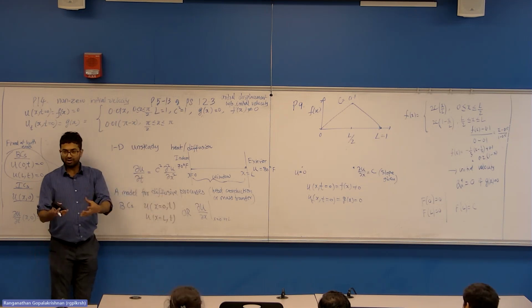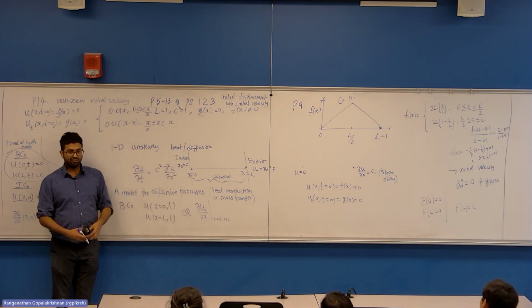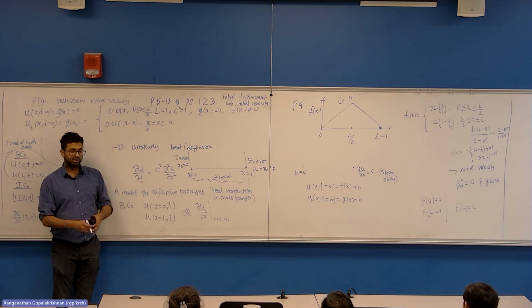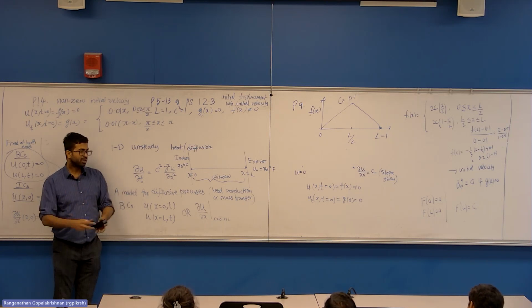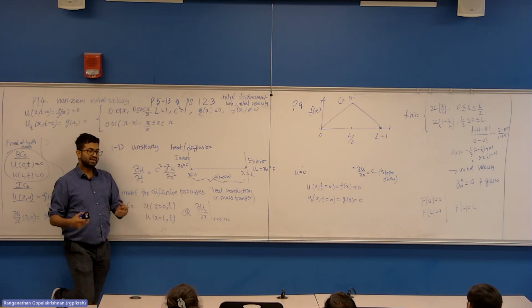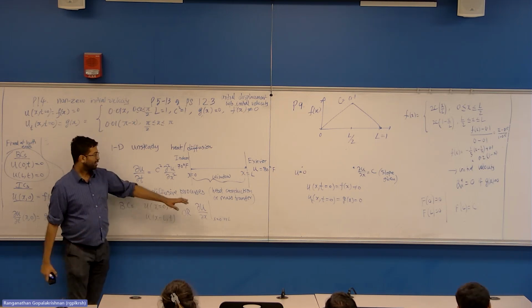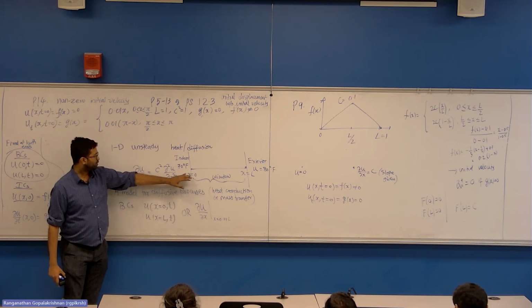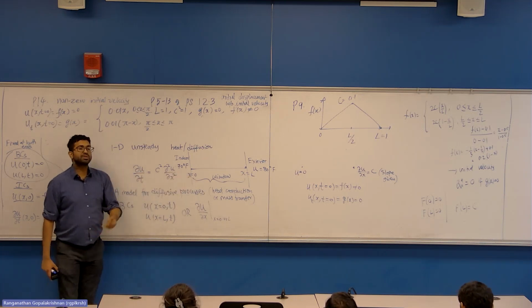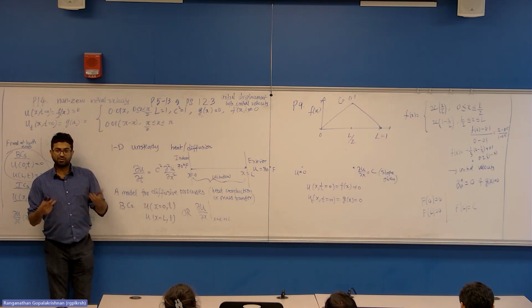When you boil something on the stove, are you setting temperature or heat flux? Heat flux, right? Because you set the burner at a certain rate. You know what your fuel is, propane, butane, whatever it is. It's going to combust and release heat. And if the combustion is steady, the heat flux into your vessel is going to be steady. So it's a constant heat flux boundary condition, which is experimentally easier. But in terms of calculations, that will be a slightly more involved one than specifying temperature. If you were to specify temperature in a heat transfer experiment, what would you need to do?